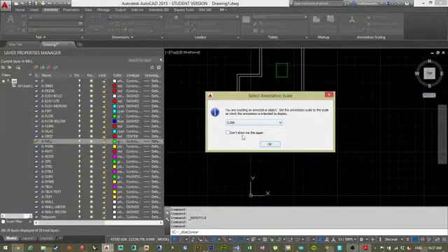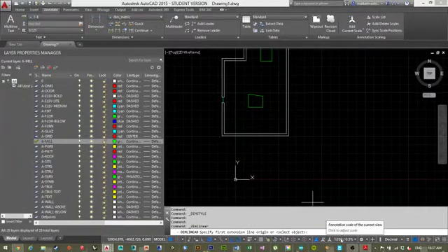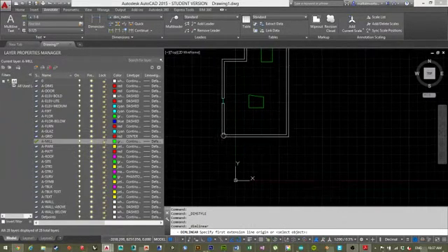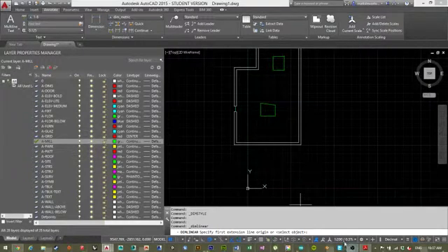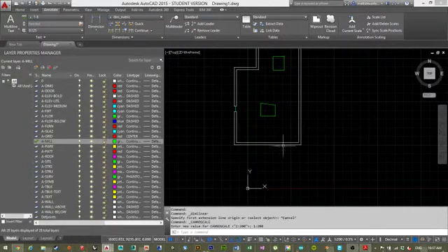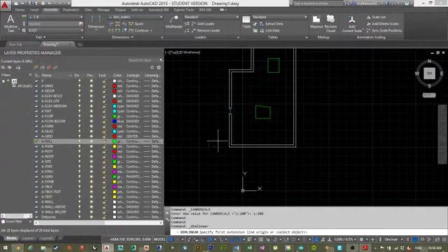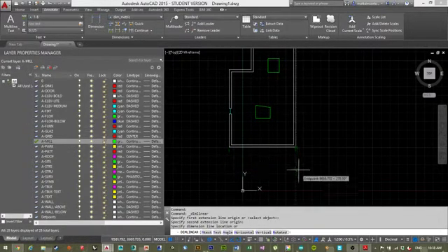And there is a way to change that later, and you'll see that down here, even though we're still drawing in 1 to 1, you can set this to 1 to 200 just because we know that we're printing. That's what we're using. So for this dimension, you click the start, click the end, and then pull it out wherever you want.